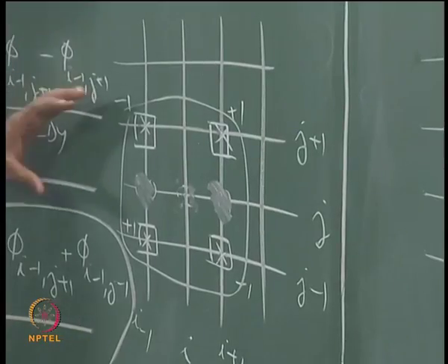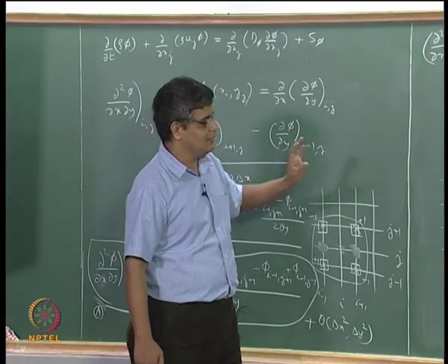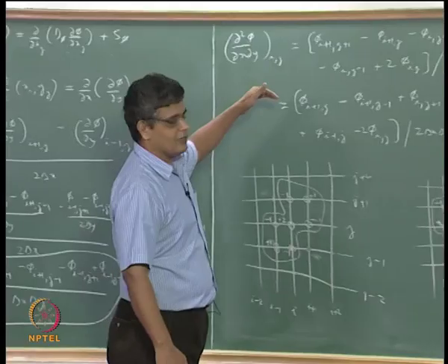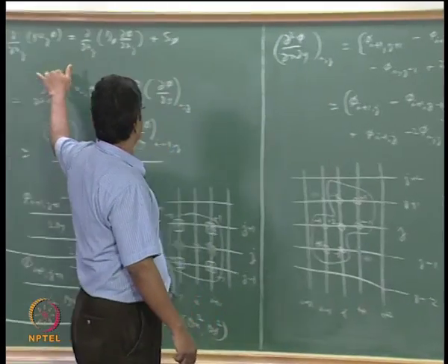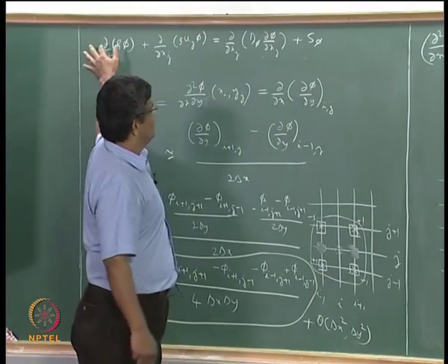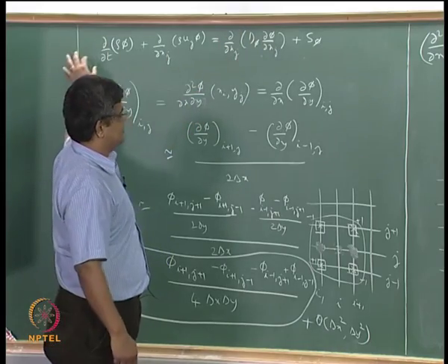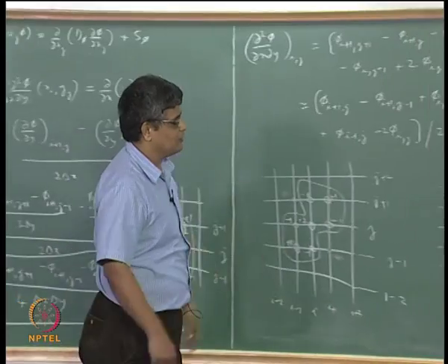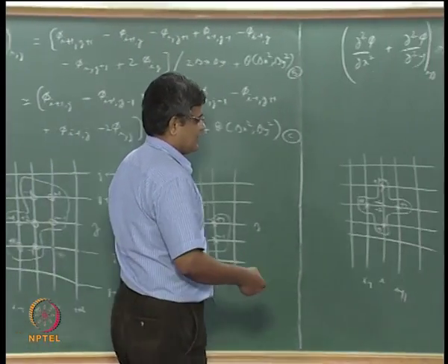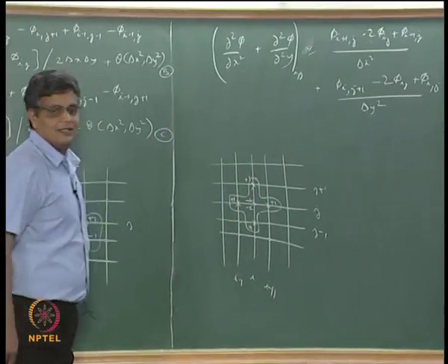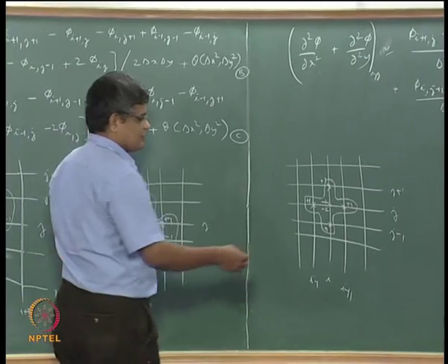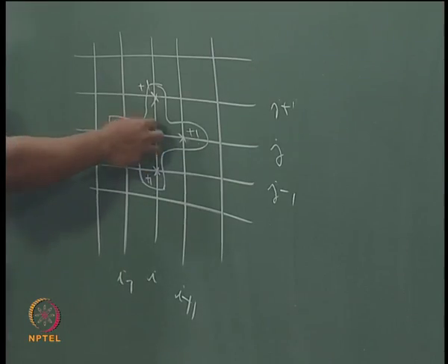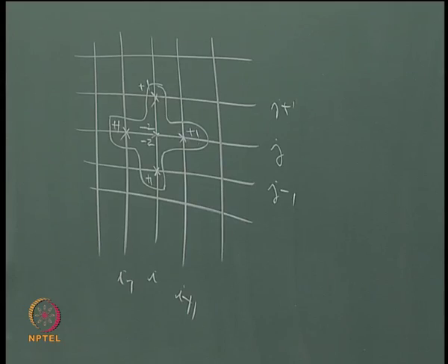So it all boils down to the computation molecule, and whenever we write a finite difference approximation for each term, the overall resulting equation should be put up in the computation molecule, and we should check whether or not we are satisfying the preponderance of the coefficient associated with the central grid point. Okay, so this is important.